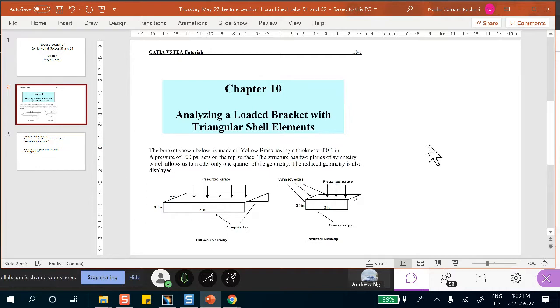Now, generally speaking, the condition for being able to solve it with shell elements is this. Remember, at every point in your solid object, you have 6 components of stress. This is the stuff that Dr. Green did for you, okay? There's 3 normal and 3 shears.